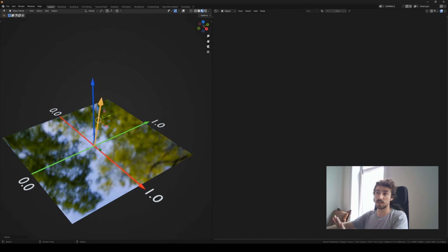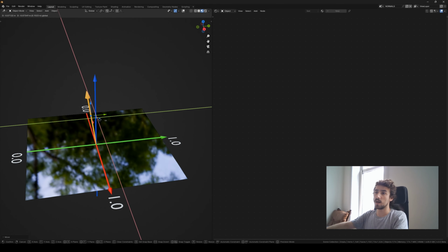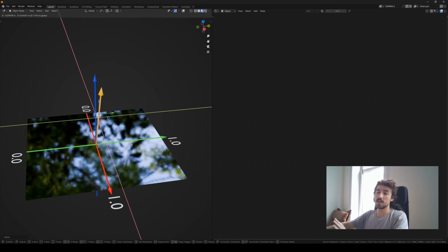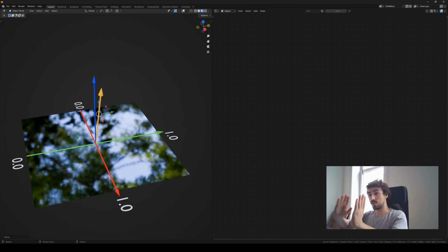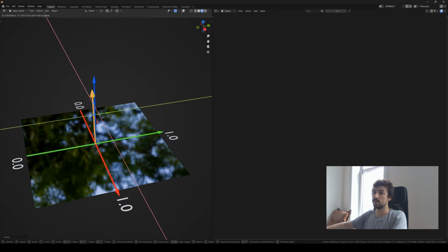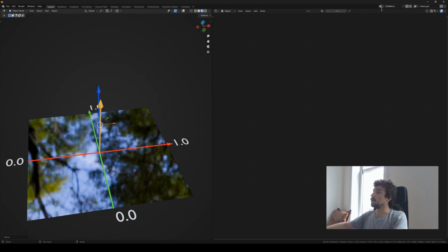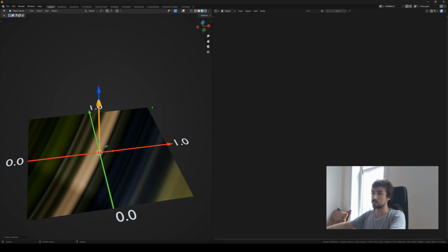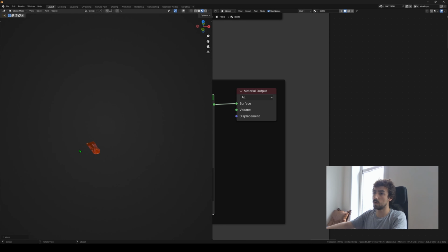The surface itself is exactly the same, but we are just cheating the way it reflects by feeding it this normal map. So on each pixel, we will say, actually, the normal of this surface is slightly more to this angle, slightly more to the x-axis or the y-axis, and this will impact the reflection we have. And so we can use this thing to do our flakes, basically.